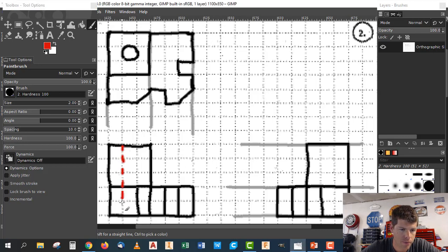through for this hole. Same thing here, but remember, we're not going to overlap right here because the visible line is more important than the hidden line. So I'm going to start at the top, draw it down, and stop right there. We know the hole goes all the way through the part, but I'm not going to overlap that visible line. That visible line's too important. Same thing over here. I know that hole goes right here. I'm going to stop, and then here I can carry it all the way down through.